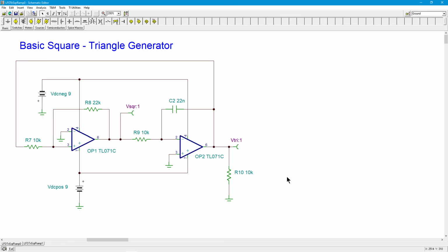But this thing is just going down, down, down. Eventually, if we wait long enough, this voltage will get so negative that it will pull this node below ground, right? So your other pin on this op amp is set to ground. So when that happens, the inverting input is more positive than the non-inverting input. And that flips the polarity of the differential input, which means it flips the polarity of the output. So now, instead of being positive saturation, this thing goes to negative saturation.